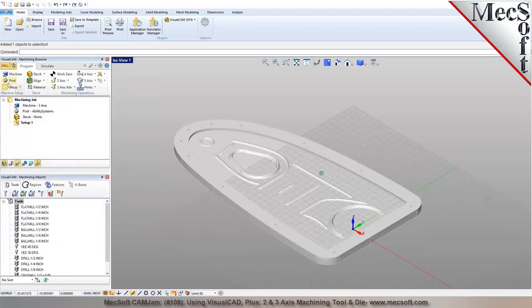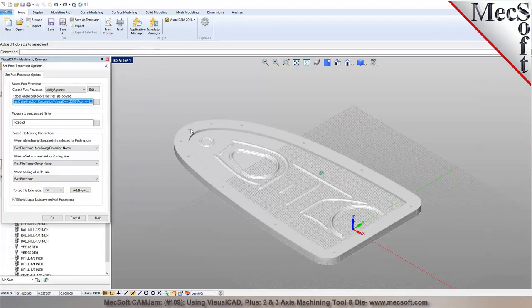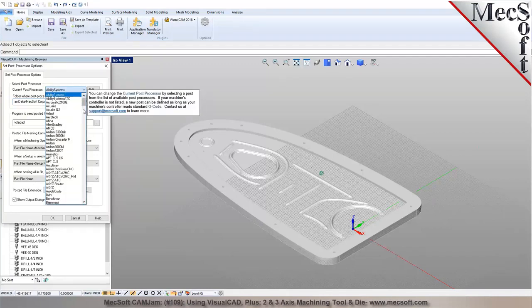In the next step, you can select the post processor. This would be the machine tool that you would like to generate your NC files or the G-code output files for. And from your notes, I see that you mentioned an Axis AXYZ router. Yeah, that's one of them we write for. Okay, so we do have several different posts for Axis routers.